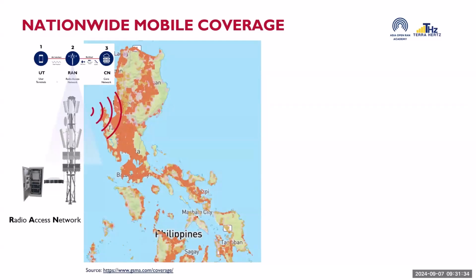So typically you will hear the word cell site. So cell site is part of the RAN. So cell site is one part of the radio access network. Pag sinamasama mo yung cell site, you will build what we so called the radio access network. And the cell site is composed of antennas, as mentioned by Engineer Dika, jumper cables, remote radio unit, CPRI or the common public radio interface, the baseband unit, the power supply, and the transmission, and including the tower structure.